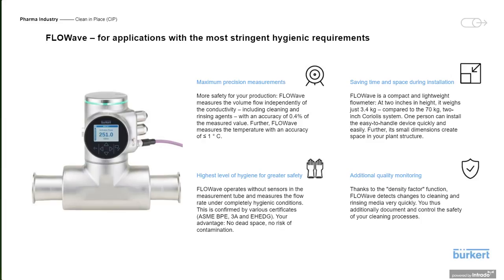In terms of footprint, the 2-inch FlowWave is 9.8 inches long, 4.9 inches wide, which would be into the screen, is what we consider width, and 7.1 inches high. That comparable Coriolis, and this is the smallest one I was able to find across multiple manufacturers, is 22.1 inches long, 7.8 inches deep, and 17.5 inches high. So I think even without doing a volumetric calculation, it's very obvious that the weight and the footprint advantage definitely goes to FlowWave.